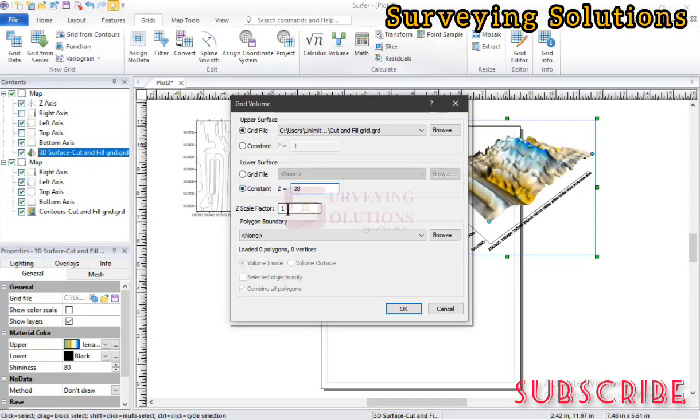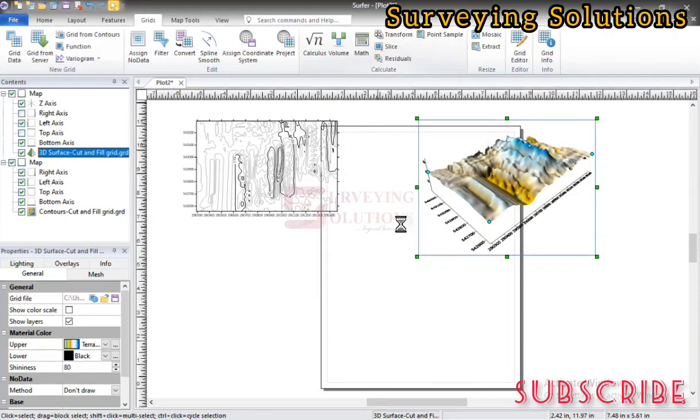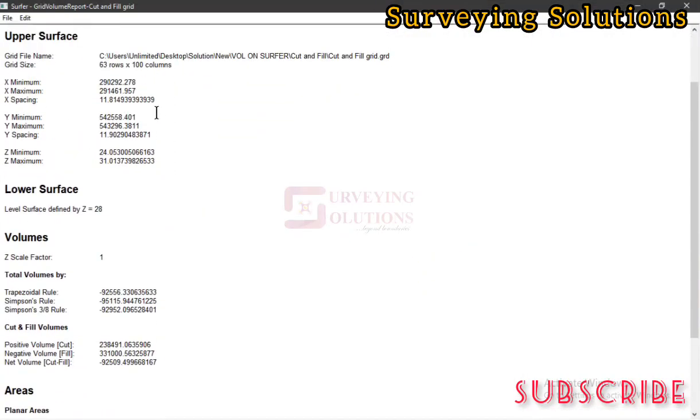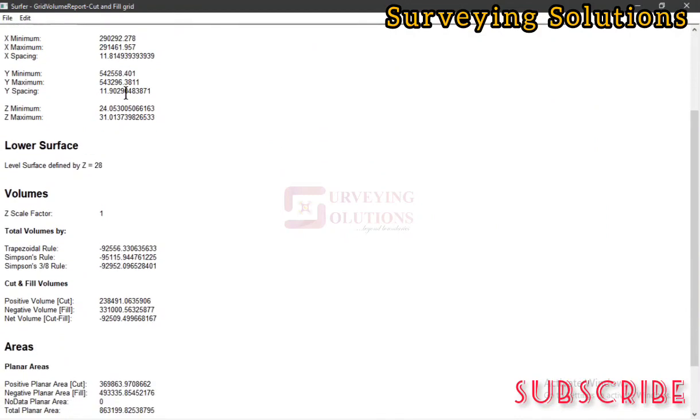Then our scale factor is 1 because all our units are the same, right? Good. We don't have a polygon, so upon setting up all of these on your grid volume window, ensure you pay attention to why we chose 28, right? Good. So just click on finish. All right, now we have the grid volume computation, and then we have our report.